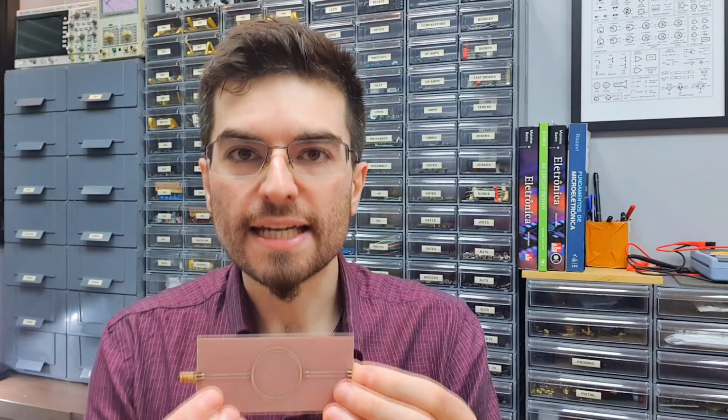This is key because I see a lot of experiments about resonance where the resonator is actually loaded, and in that case you would not be measuring the correct resonance frequency of the unloaded resonator. So the idea here is that we need to adjust the gaps to keep the coupling very, very low, but not so low that we cannot measure it. I realized that the coupling needs to be controlled so the transmission is not greater than negative 25 dB.